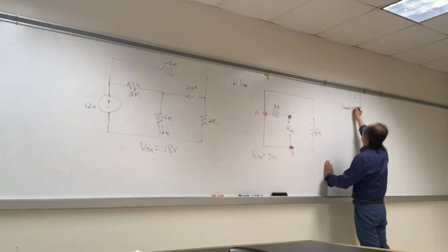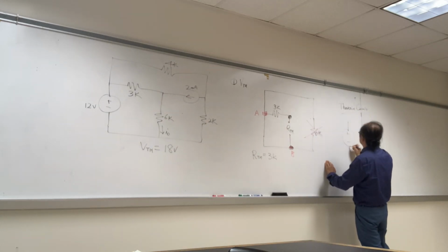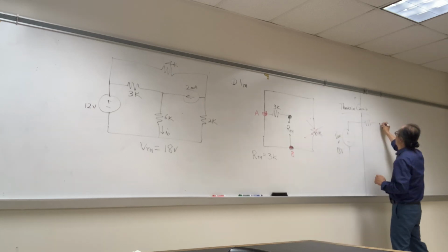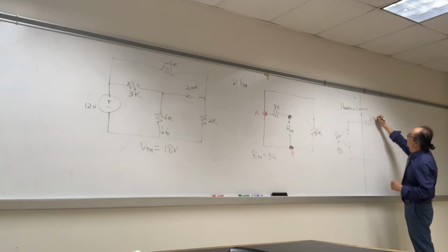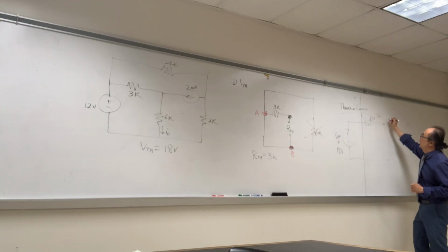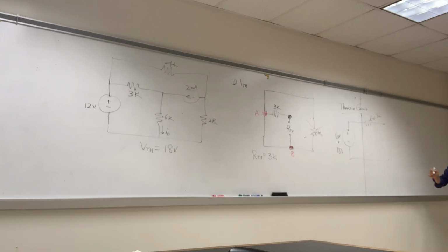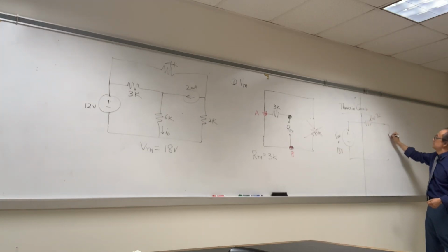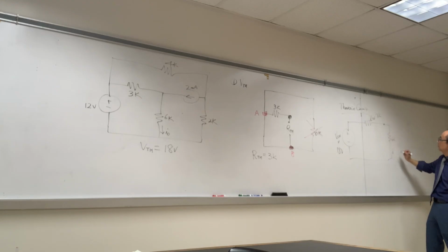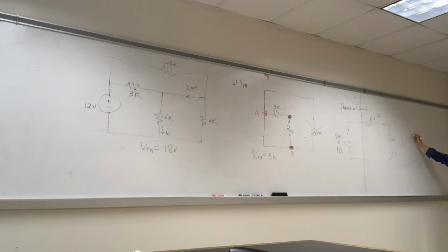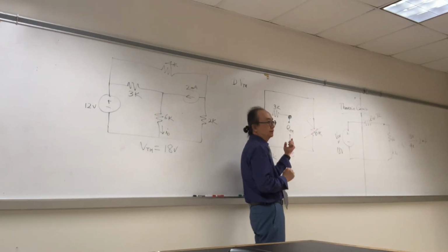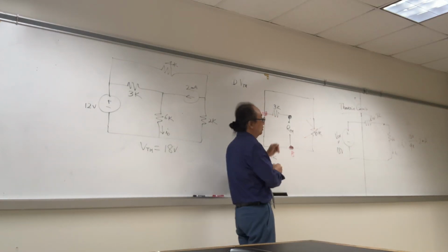Therefore, our Thevenin circuit is going to be plus minus VTH, which is 18 volts in series with RTH, that is 3K, and our load that we took out is 6K, and the current going downward. So I sub 0 is what? V 18 over total R 9K, that is 2 milliamp. Yes, so when we do this finding RTH, we need to assign the node.